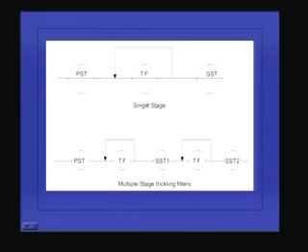So here what is happening, the trickling filter is here, and whatever effluent is coming out is not even going directly to the secondary sedimentation tank. Before that it is getting recycled, and a portion will be going to the secondary sedimentation tank, and after the sludge settling, the treated effluent is going out.